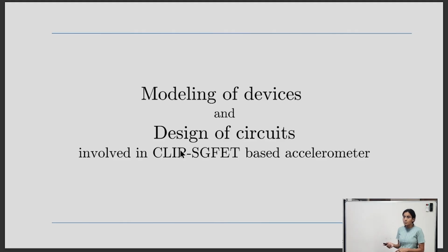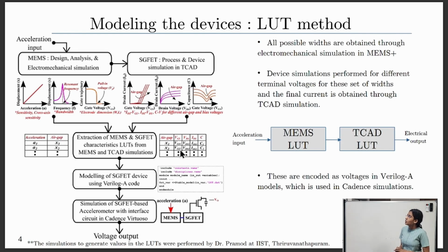First we will discuss modeling of these SG-FET based sensors, and then the design of circuits. The circuits are designed in Cadence in UMC 180 nanometer technology. We have used a LUT based method to model the device.